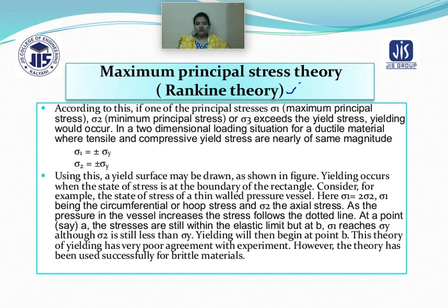However, still this theory has been very successful for brittle material, because you can see that for the maximum principal stress theory, what basically occurs is your maximum principal stress is getting to the extent of your sigma y value, and in case of minimum principal stress, you can see the value of sigma 2 is still less than your sigma y value. So, yielding at that particular point already starts beginning for that particular section.